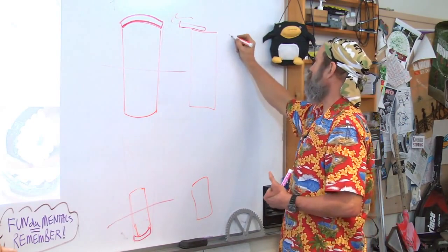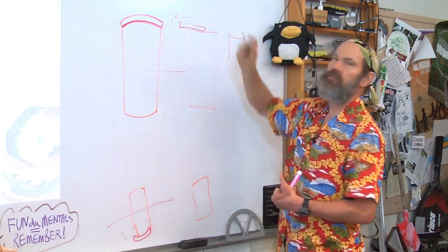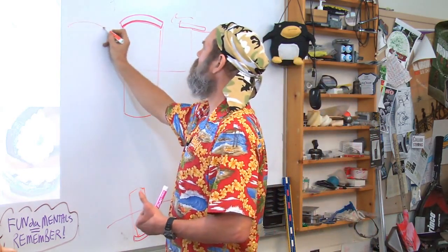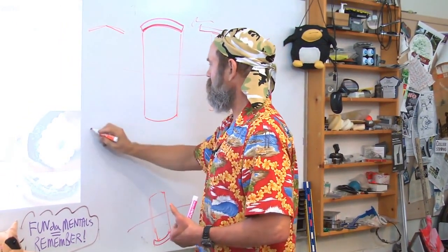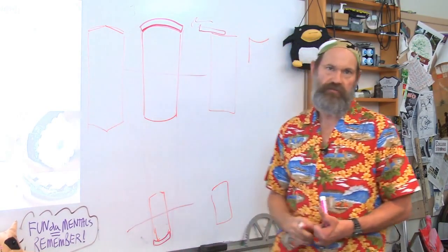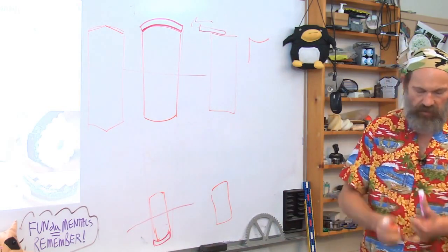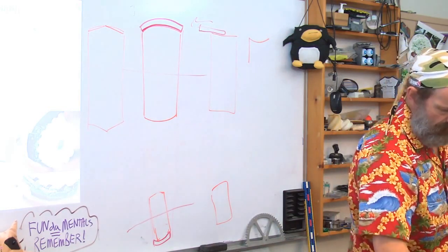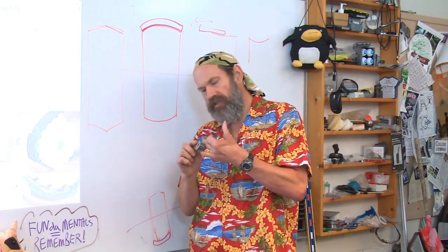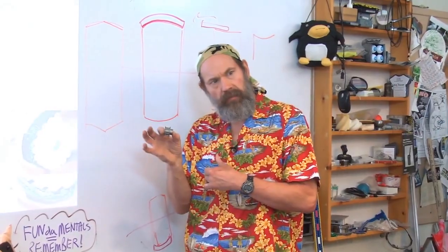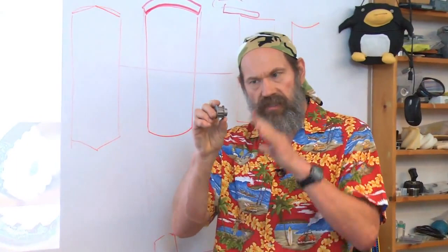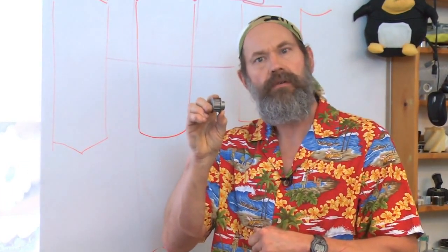Try reciprocity and do a concave pulley, it also comes off. Yeah, but this is such a pain to do. Yeah, this has got to be the same as this, so we'll just peak it like a triangle. Yeah, let's do that. Build a machine, turn it on, ready to go. Belt walks off. Okay? So now you think, he was talking earlier about timing belts, and they've got these little flanges on them to keep the belts aligned in place. Why don't these timing belts have a little bit of curve in the teeth?